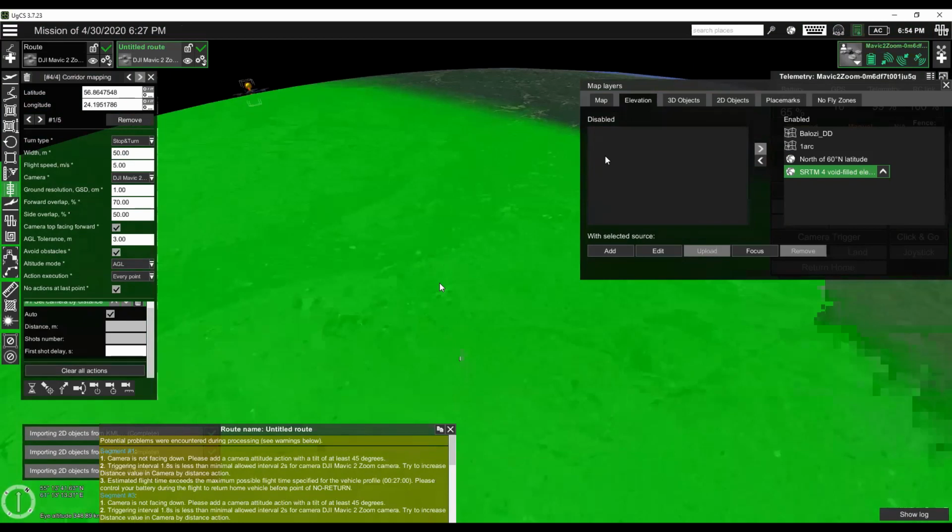It's not very accurate, and it's a ground elevation. It will not contain the trees, the buildings and other obstacles. Using the software, it's just not possible to predict all the obstacles that might be between the takeoff location and the first waypoint. So using the first waypoint at the road and observing the area is critical for safe flights.